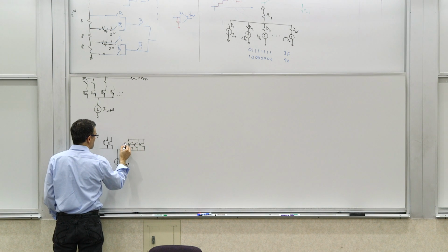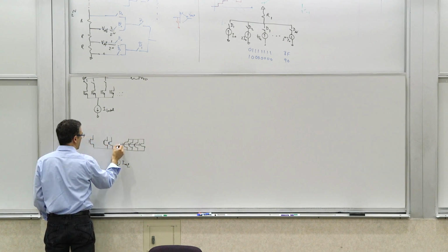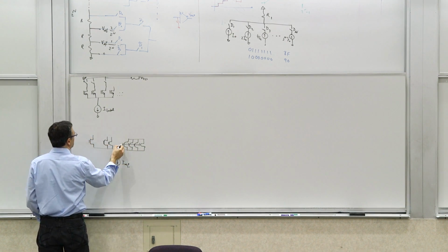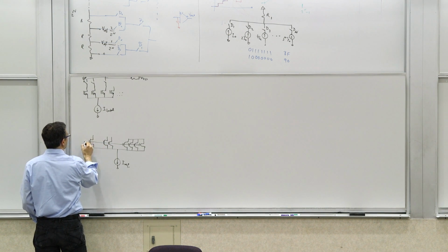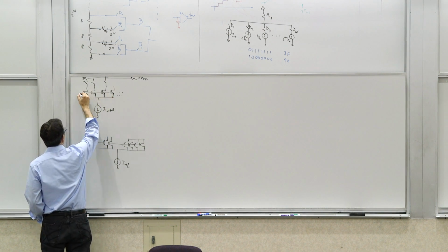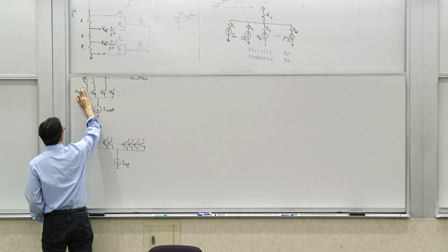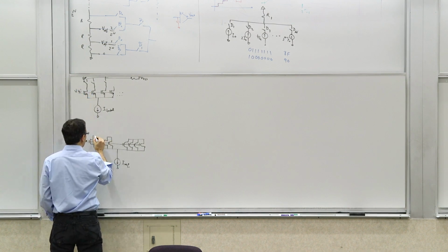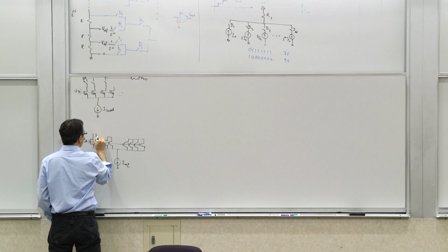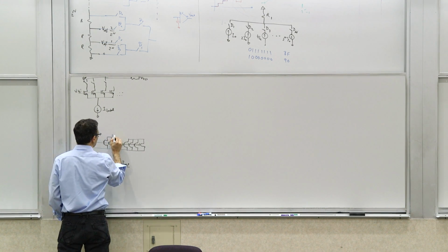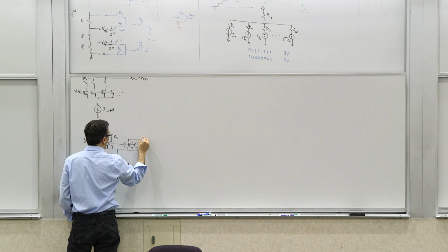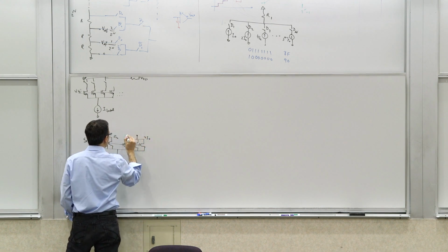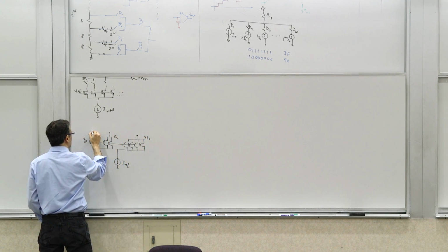You can clump these, and then you have essentially these are at some reference level, right? The same thing here. These are all V bias. Let's not call it VREF, V bias. And then these are clumped together. So this basically gives you I0. This gives you 2I0. 4I0, assuming that you always are dumping the current somewhere, right?